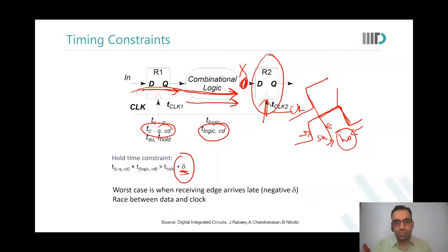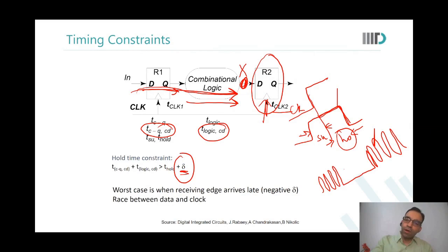But for example, you also said the input should be stably available at the output, and for that we consider the propagation delay, because we are not sure that the data will be stable at the output Q pin of register 1, because then that only will be propagating towards that. Let us say there are these glitches that appear. Okay. And let us say this is the sampling edge. What do you want? The first glitch should happen after hold time, right?